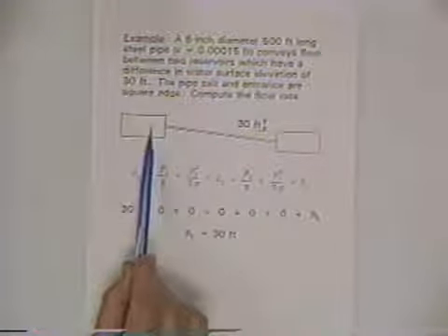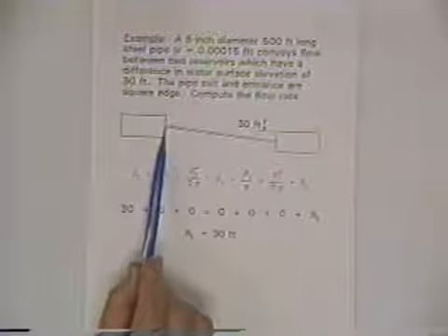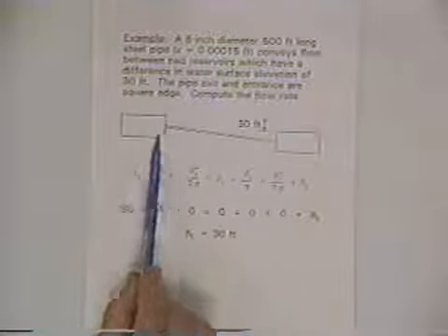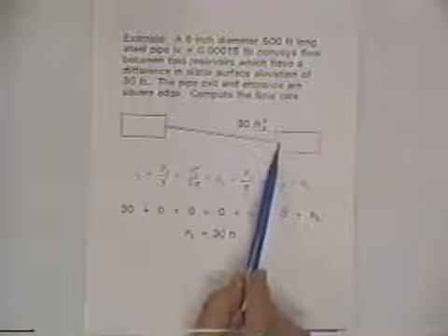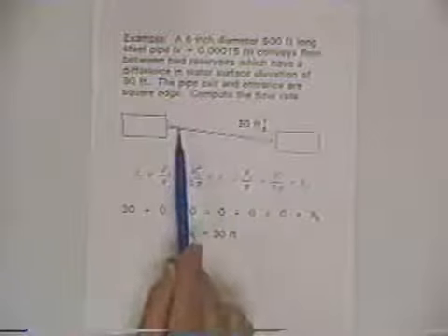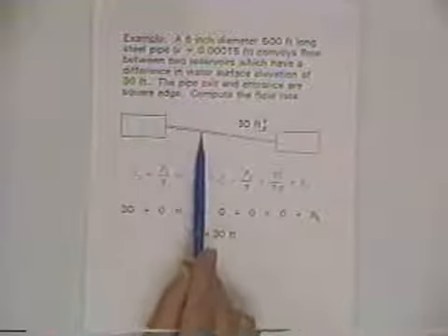But we also have an entrance, because the water goes from the storage tank into the pipe, so there's an additional head loss there. Plus, the water goes from the pipe into this container, and there's an additional head loss there. So that'll give us a chance to include in this head loss term the minor losses as well as the frictional losses, in which Darcy-Weisbach tells us how much head loss occurs along the pipe.